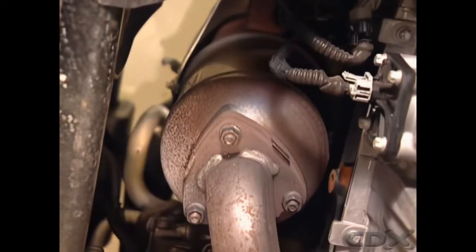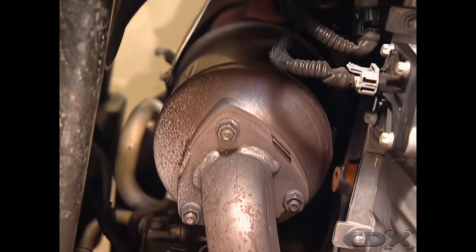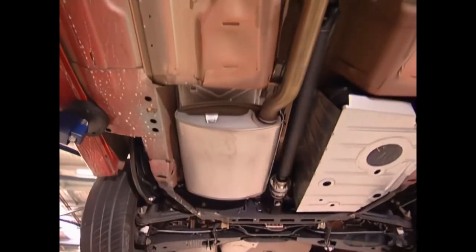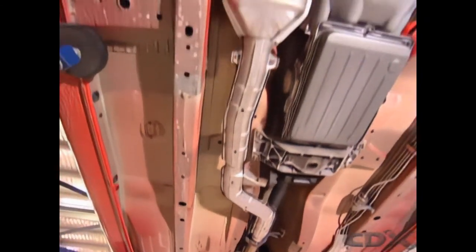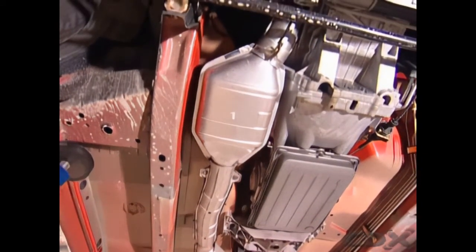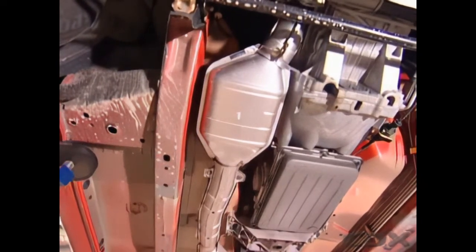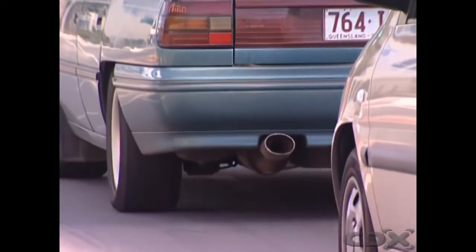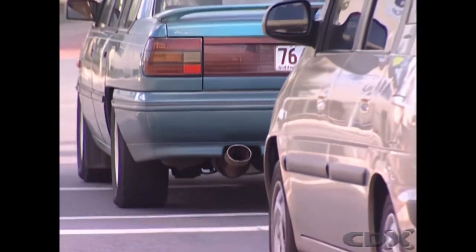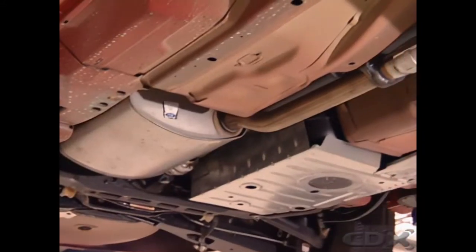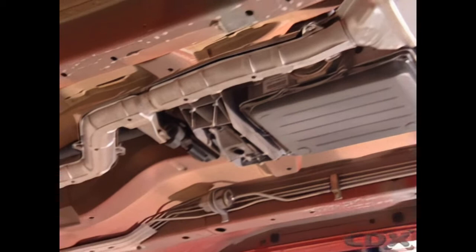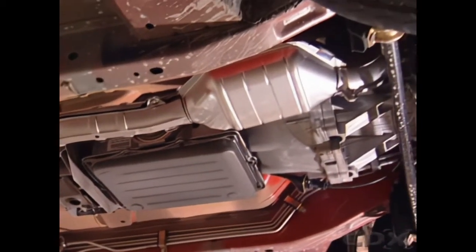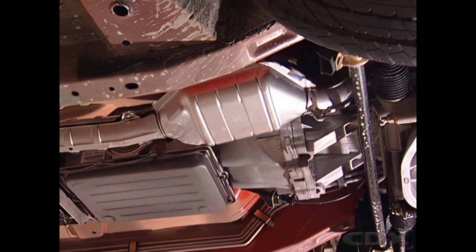A catalytic converter fits into an exhaust system and resembles a muffler. It's located close to the exhaust manifold so that it can reach its operating temperature as soon as possible. The catalytic converter operates at higher temperatures than a muffler. In this location, the hotter exhaust gases reach the converter earlier, and it heats up and starts to operate faster. Careful consideration to the location of the converter must be made, as this may also reduce the life of the converter by exposing it to extremely high temperatures.